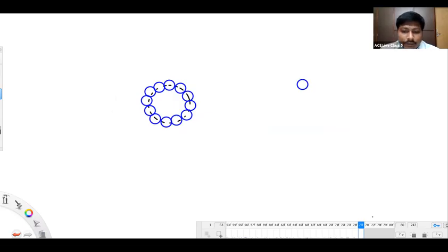But to have that support, to make all the strands in that shape that we have shown, we used to keep some arrangements, some strip kinds of arrangements, in such a way that all the strands are kept in the form of a circle as we have shown in the figure. So it's a hollow stranded conductor we can call. It's a hollow conductor, but it's stranded.